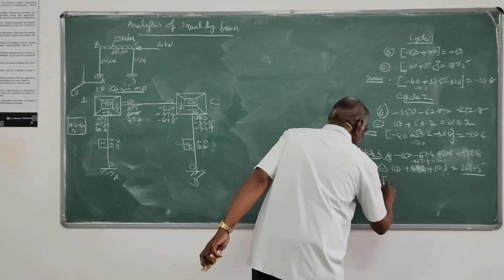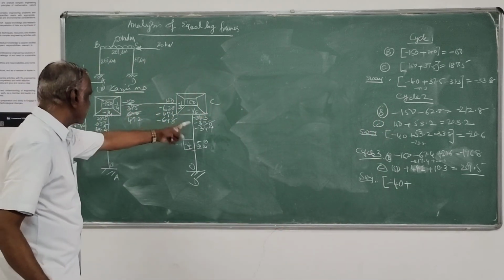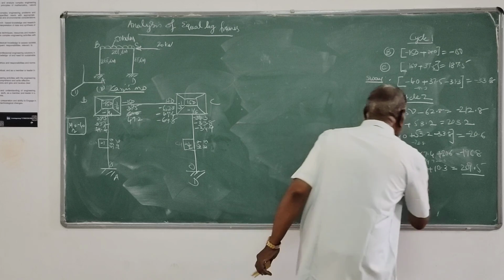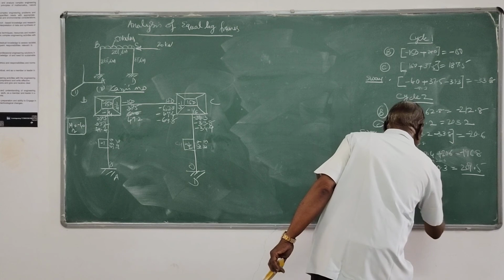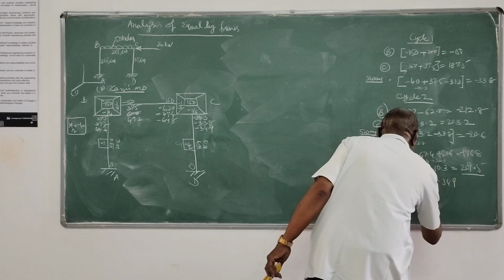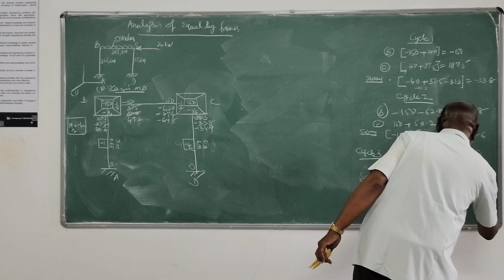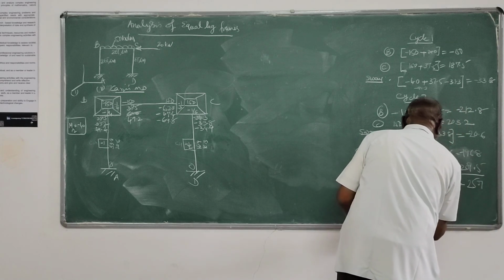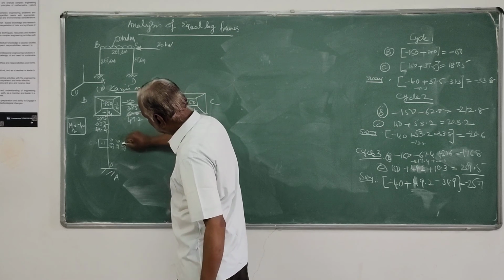Sway contribution, that is story moment plus sum of the rotation contributions at these ends. 49.2 minus 34.9, minus 40 plus 49.2 minus 34.9 equals... So this is equal to minus 74.9 plus 49.2, which is nothing but minus 25.7. That multiplied by minus 1, it is 25.7.